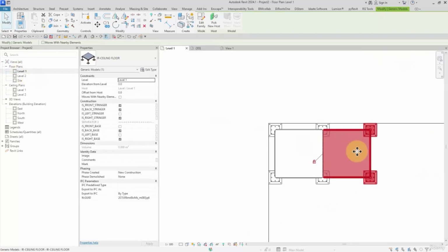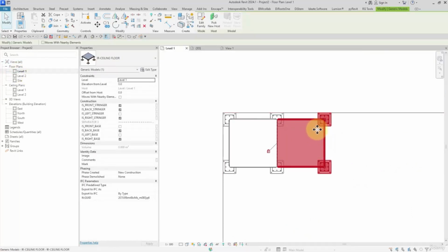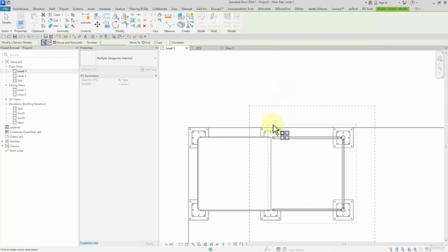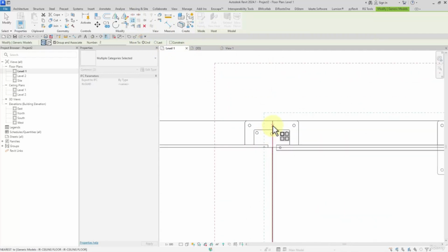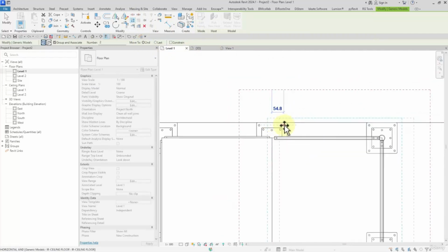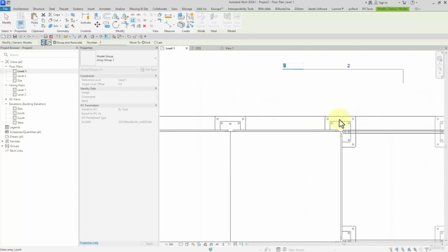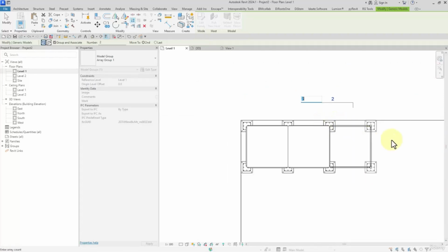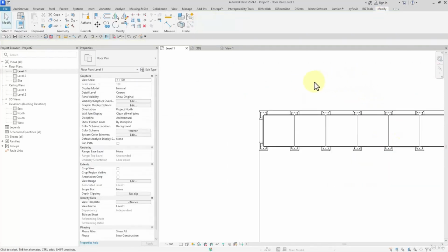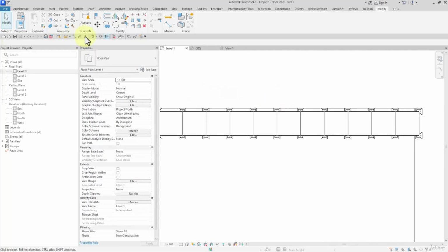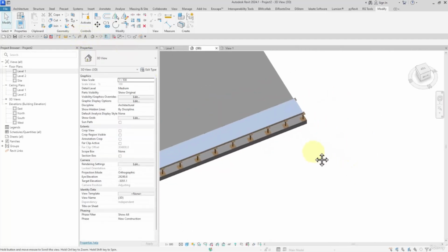Okay, opening the plan view, and right now I can propagate this. Move to second by using array from the axis to the next one. How many? 10. Watch this. This is the result.